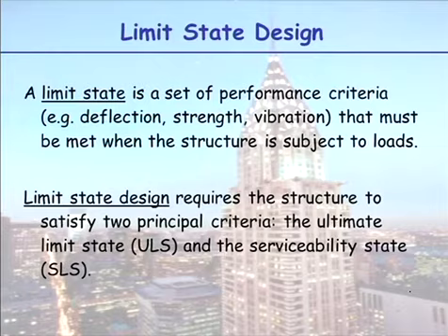So when our limit state design, limit state is a set of performance criteria, strength, deflection, vibration, that must be met when the structure is subject to loads. We don't just design so the building doesn't fall down. You may walk across this floor and I go, assuming it's on the 10th floor of a building, and I'll go, it's perfectly safe, walk across it, and you start walking across it and it starts bouncing. And I go, don't worry about that, it's not going to fall down, okay? You're not happy with that. So we design for deflection, for serviceability, as well as strength. And we put equal weighting on both designs, but the variation comes in our load factors.